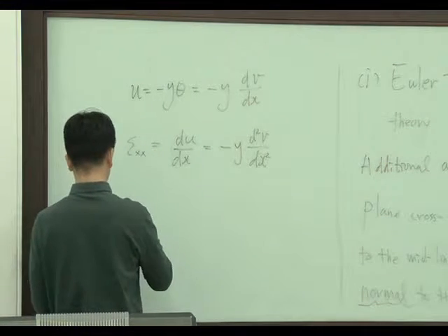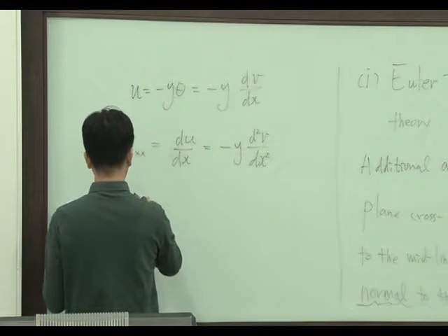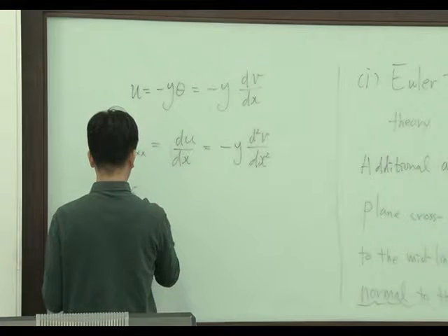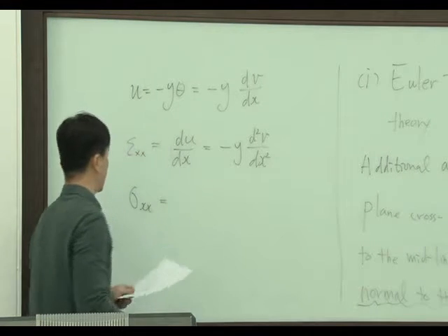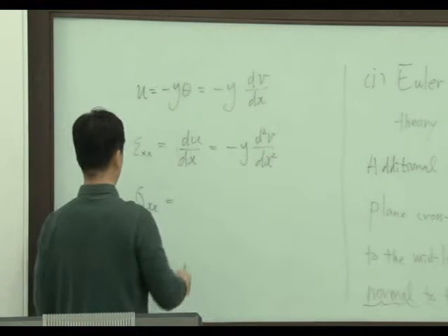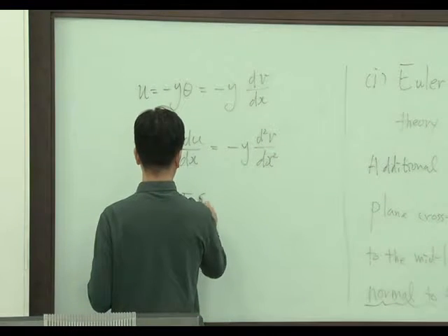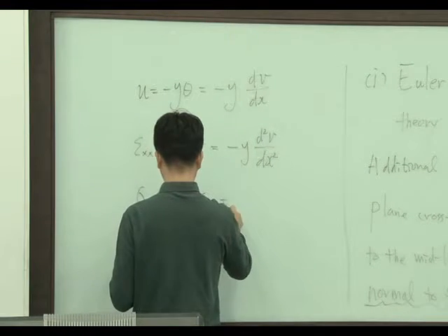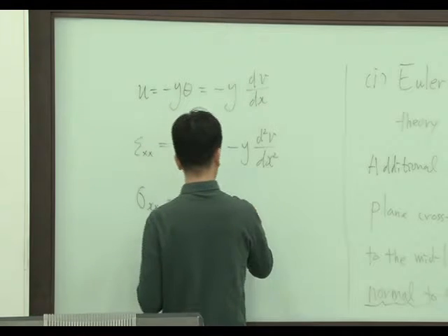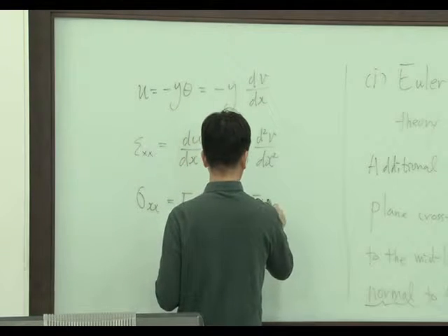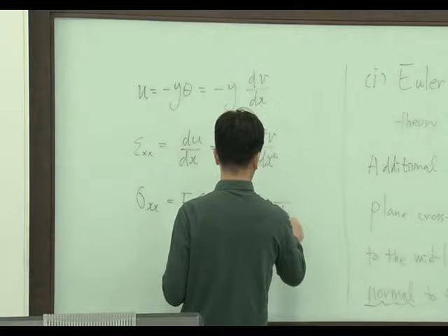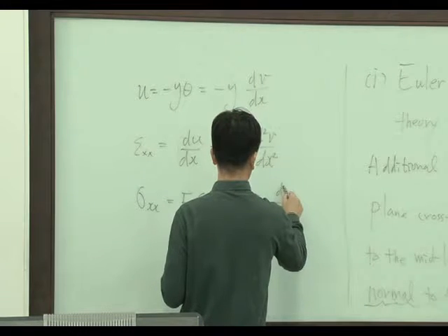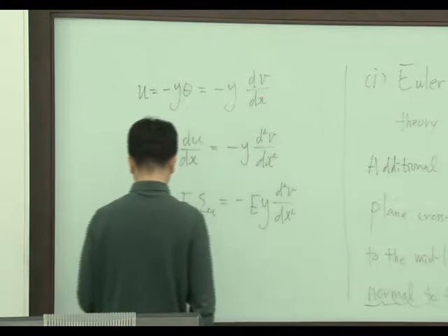Also, stress xx can be calculated by the material law. E strain xx equals minus E y d2v/dx2, right?